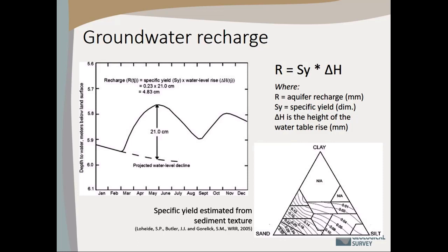I've done other monitoring where I've come up with similar estimates by looking at a rainfall event, the water level change divided by the rainfall in the same units, and you end up with values like 0.05 or 0.06 and so forth, which are on the scale of what's presented here for this readily available specific yield. So over the span of a couple of days after a rainfall event, this is the amount of soil porosity that you're filling up.